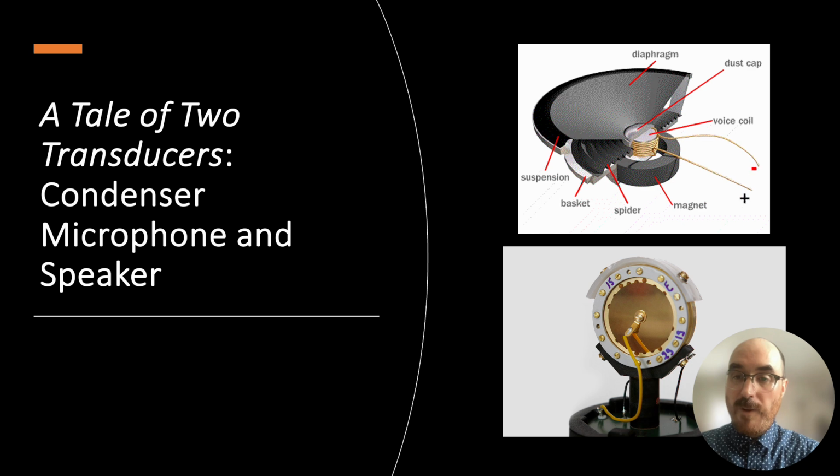Basically this positive and negative signal, the alternation of that, actually pushes the speaker, which then pushes the air. A microphone works sort of like a speaker in reverse, right? The air pressure disturbances that it perceives, it then turns into electrical signal that it puts out through the cable into your mixer or into your interface. So it's really important to think about those two technologies as mirror images of one another.